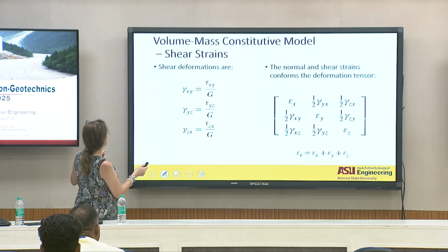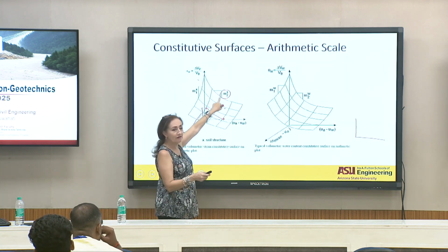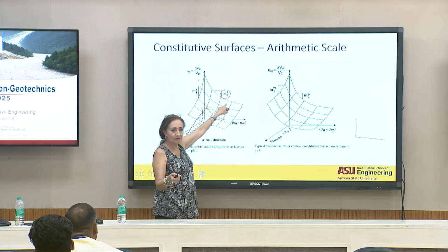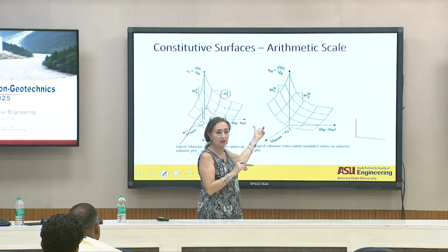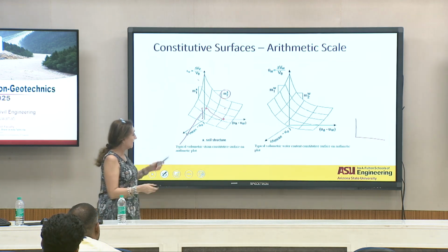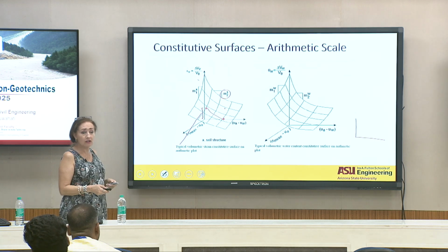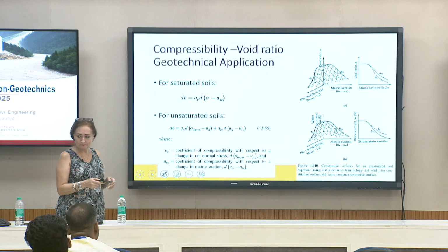We consider this to be elastic in a certain range of values, and then we use another elastic model for another set of values. You can make it as non-linear as you want, depending on the values you get, but you need to be careful that what we're using here is linear elasticity. But certainly, out of a surface like that, you can do any combination of load conditions, and you can have collapse in an expansive surface.